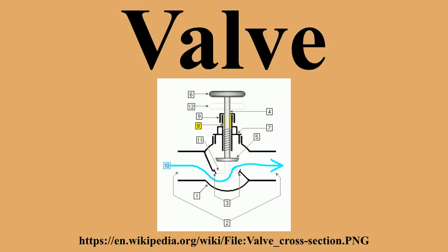Some valves are specially designed to regulate varying amounts of flow. Such valves have been called by various names such as regulating, throttling, metering, or needle valves. For example, needle valves have elongated conically tapered discs and matching seats for fine flow control. For some valves, there may be a mechanism to indicate by how much the valve is open, but in many cases other indications of flow rate are used, such as separate flow meters.